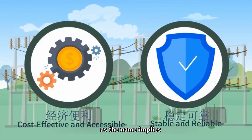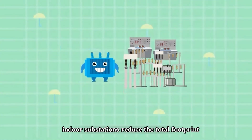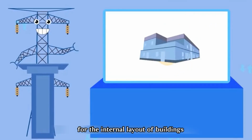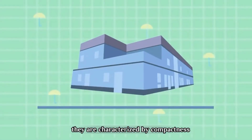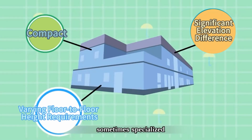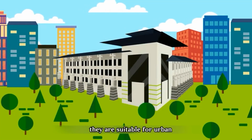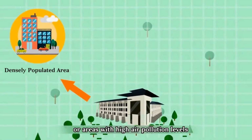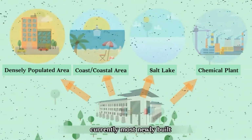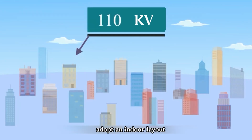As the name implies, an indoor substation refers to one where the main equipment is placed indoors. Indoor substations reduce the total footprint, but have higher requirements for the internal layout of buildings. They are characterized by compactness, large height differences, and varying floor height requirements. Sometimes, specialized aesthetic improvements are made based on the surrounding environment. They are suitable for urban densely populated areas or areas with high air pollution levels such as coasts, salt lakes, and chemical plants. Currently, most newly built 110 kV substations in main urban areas adopt an indoor layout.